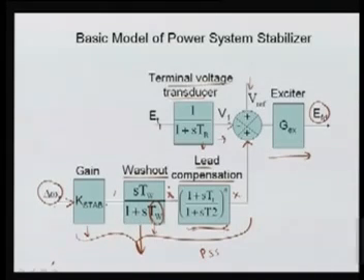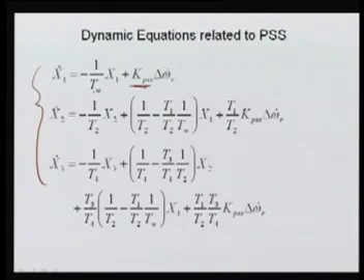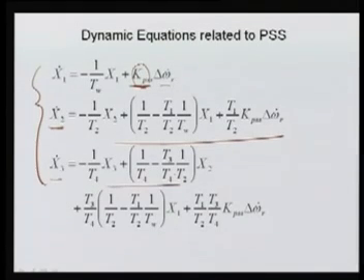So this time constant, etc., are going to be added, and you can see we are getting T upon T omega x1, K PSS, that is the gain of PSS, and the change in speed, that is the input which is coming there. Now this x2 we are again getting from T2 and T1, and this x3 if you are using more time constants, and so on and so forth. So you keep on adding the differential equations corresponding to that.